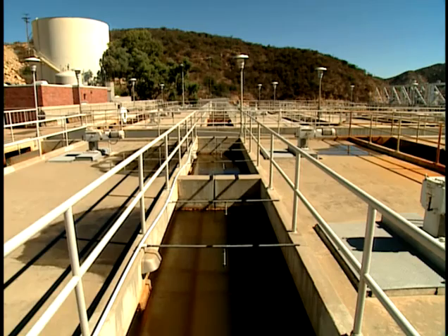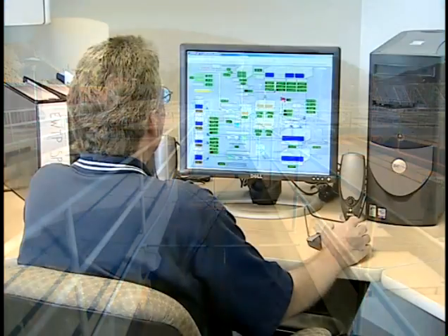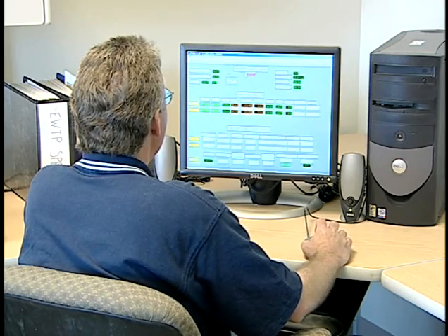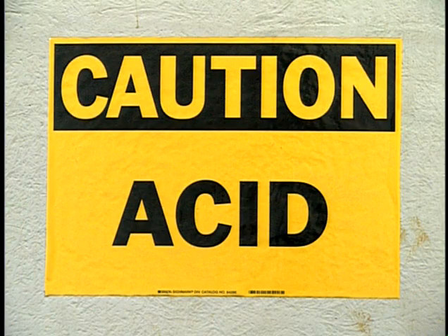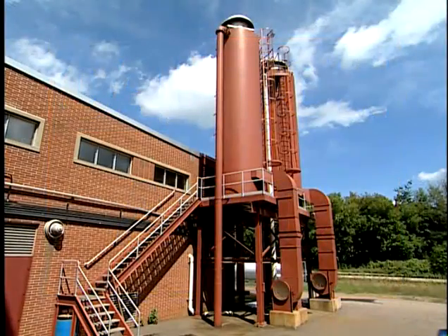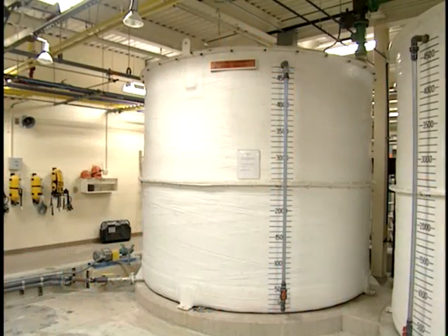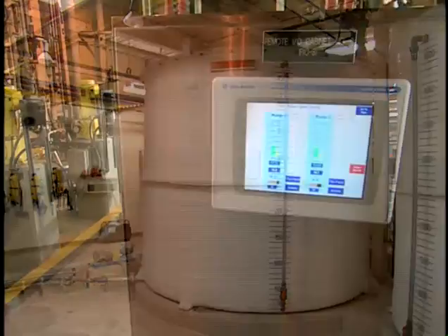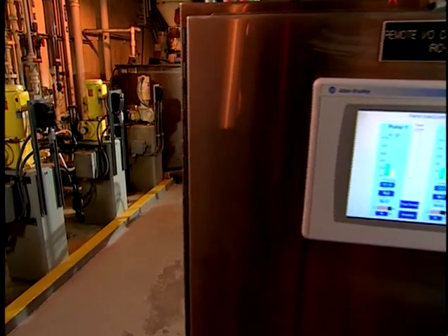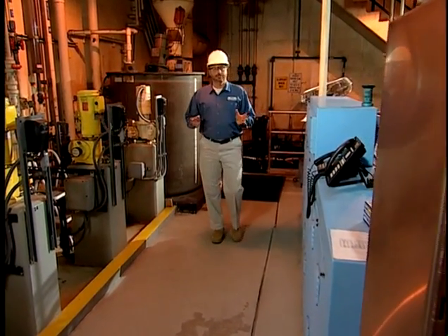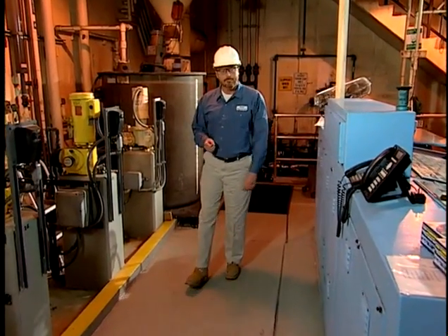Process safety management applies to those companies or utilities that deal with any of more than 130 specific toxic and reactive chemicals in listed quantities. It also includes flammable liquids and gases in quantities of 10,000 pounds or more. To fully understand PSM and its many requirements, we need to discuss how OSHA defines the term process.